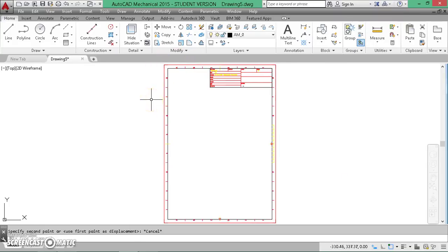Now what I want to do is move this object so that this point, which you will notice is now no longer the origin, becomes the origin once more. If you bring your cursor to this point and look at the status bar, you will see that it has roughly the coordinates of the origin, right? So in fact, what has happened is in our rotation, this point has become the origin, or rather this is the origin, and this corner is now on the origin, and we want to move this portion over there.